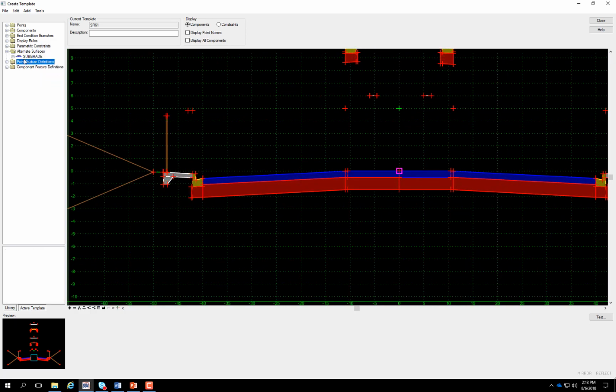And I should say, you can also click on the alternate surface, so subgrade. You may see in some of your templates that there's a stabilization alternate surface. I would delete those in your template because those were from a previous definition, and they're not accurate enough for really a subgrade surface, as we've come to find out. So we're going through our template library and deleting those.